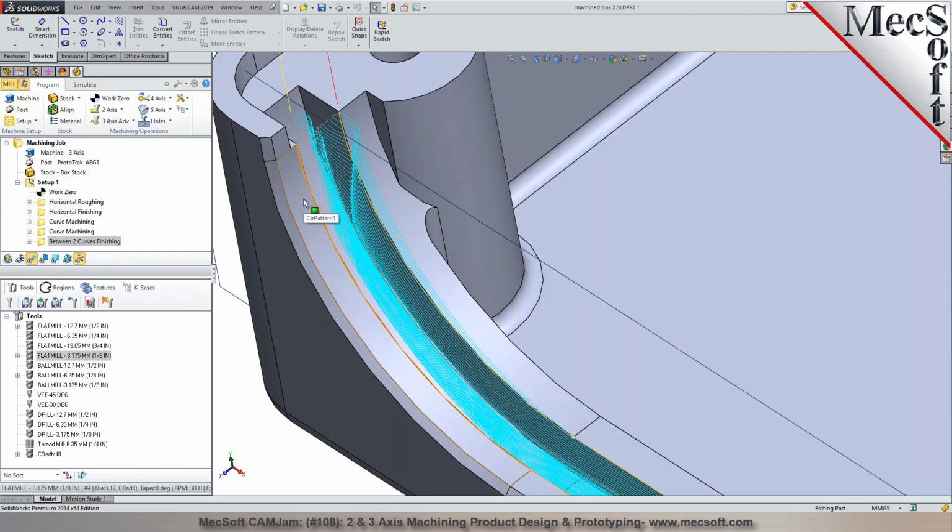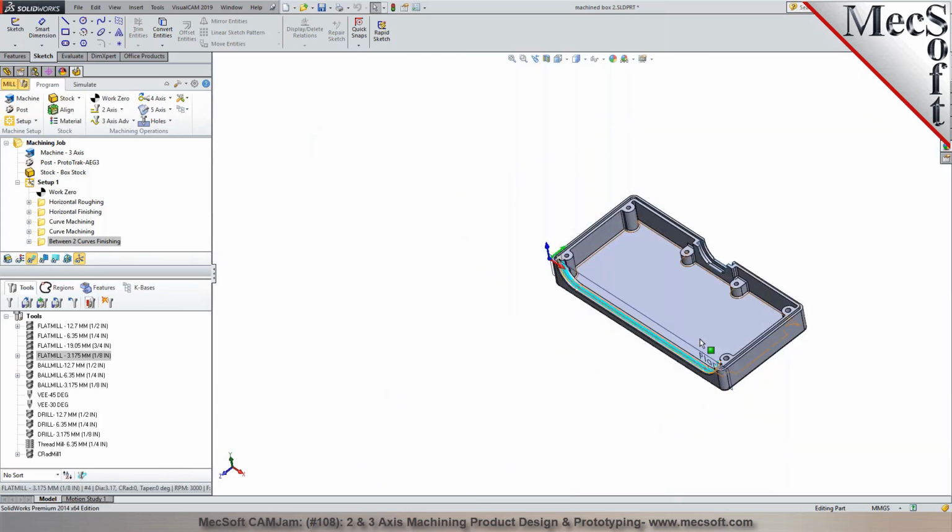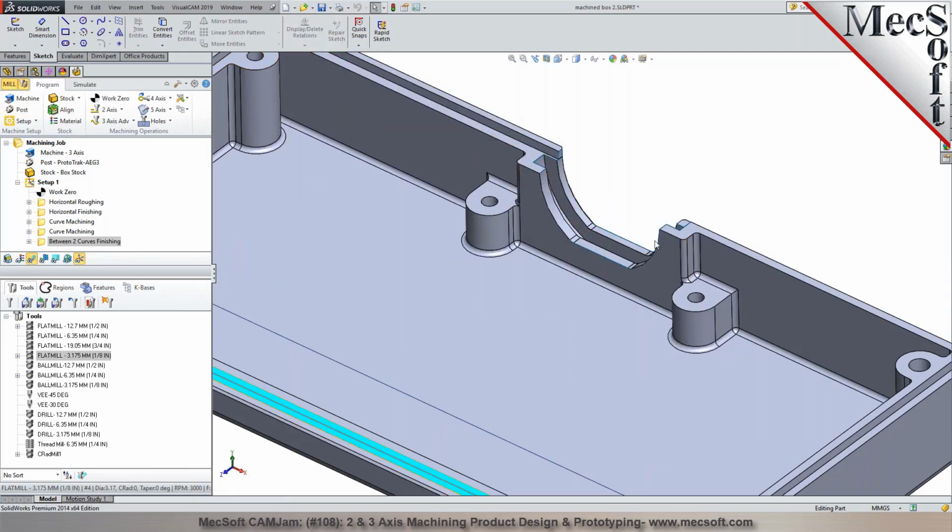So I just showed you if you just want to do a centerline pass, one cut to follow along it, I just had to do a sketch that goes on a center line, so I could drive the toolpath the way I would like it to. So the same thing can be applied over here.